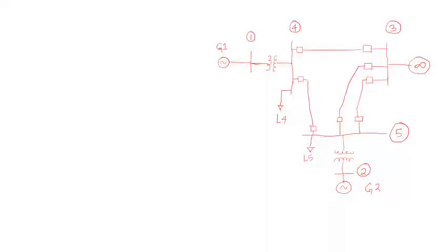In the last class we calculated our swing equation during a fault, a short circuit fault at this bus. We have seen that during the fault PE1 was 0, because the fault was near to the bus bar 4. So the electrical power goes to 0, but the electrical power PE2 was not equal to 0. Here we will calculate